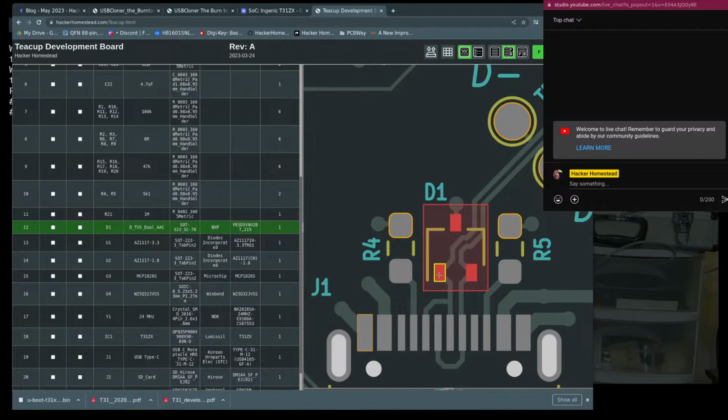That I had not modified, and at least it came up on USB. While I firmly feel that this transient voltage diode is important, it seems to be unnecessary for functionality as long as you don't have crazy voltages coming from your USB device.